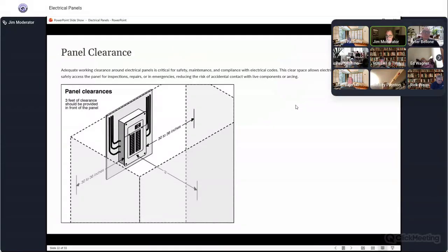You'll see a lot of homeowner special. They finished the downstairs themselves. The guy's got carpentry experience. The downstairs looks great. You're down there, and then where's the electrical panel? Well, it's behind the bathroom. And you go in there and there's a foot and you're squeezing in there to take a look at the panel. And I'm like, there's just not the space there. And the client will look at you and go, well, how big of a deal is that? And I'm like, well, if someone opens up that panel and gets an arc, they can actually bounce back and forth and get electrocuted. So we want to have 3 feet of clearance in front of the panel. Most important.